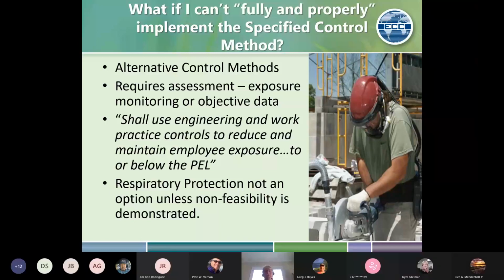We only want the respirable portion. So when we sample for silica, we have to use a size selecting device that eliminates those particle size ranges that are not in the respirable definition. Typically it's a cyclone. There are other methods you can use, but it's typically a cyclone.